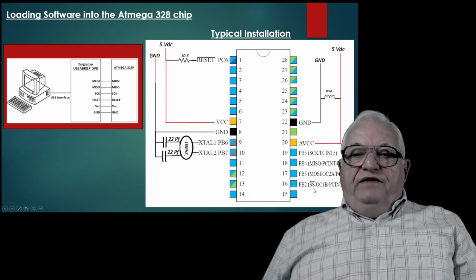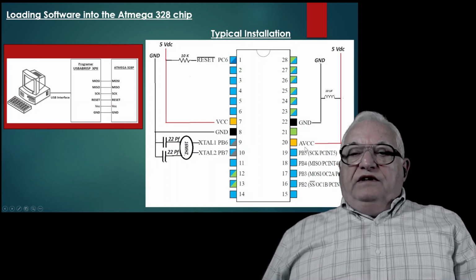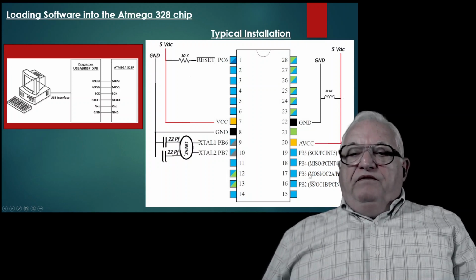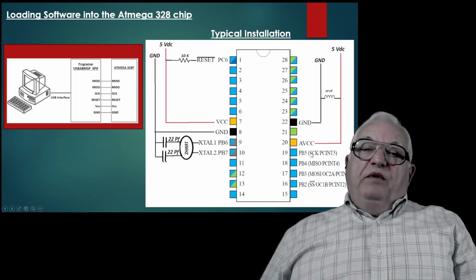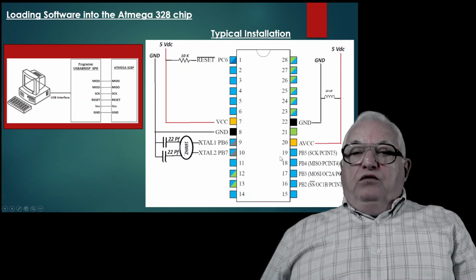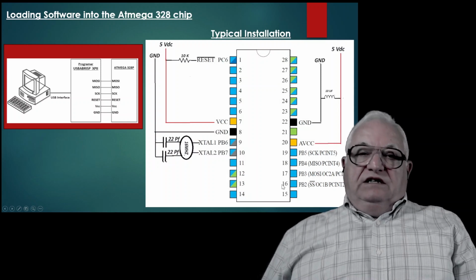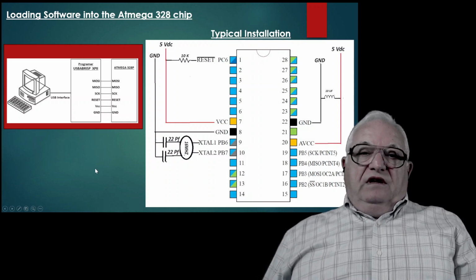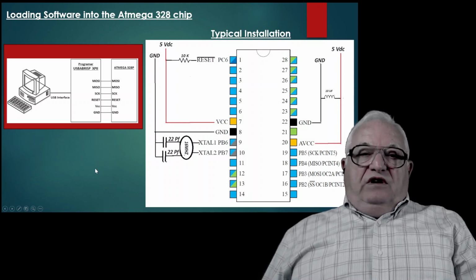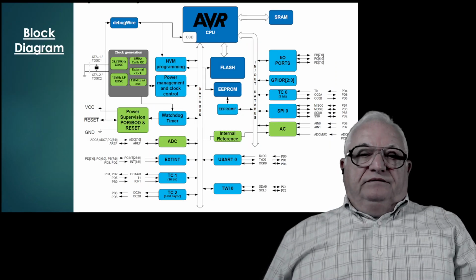Now from the physical, the software functionally would be looking at PB5, PB4, PB3, and PB2 to configure the SPI interface. However, for the hookup, they would be looking at pin 19, 18, 17, and 16. So this actually would work perfectly.